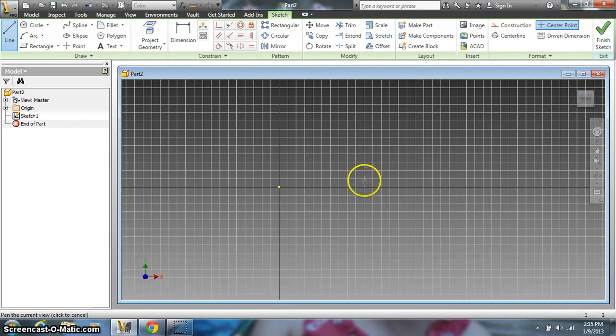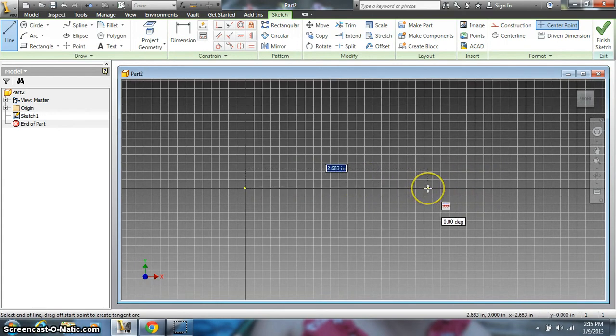And I'm going to pan over a little bit, drop this down about 2.5 inches. Now notice when I move my mouse up on the screen, you're going to see a 90-degree angle, which means it's a perfect 90 degrees, a distance in blue, and then down in the middle of that blue line, you'll see a perpendicular symbol. It means you are drawing perpendicularly. That's going to automatically add a constraint that normally you would add later on. So you can use that or not.